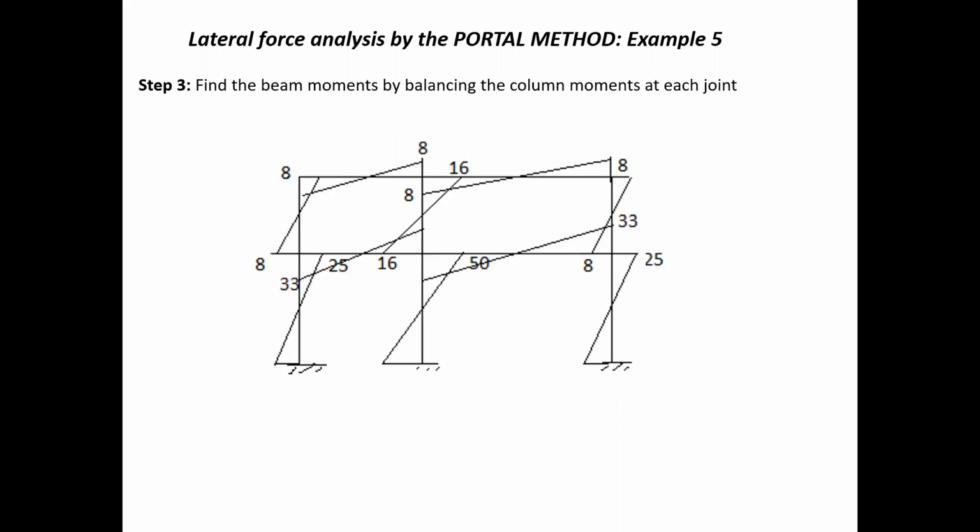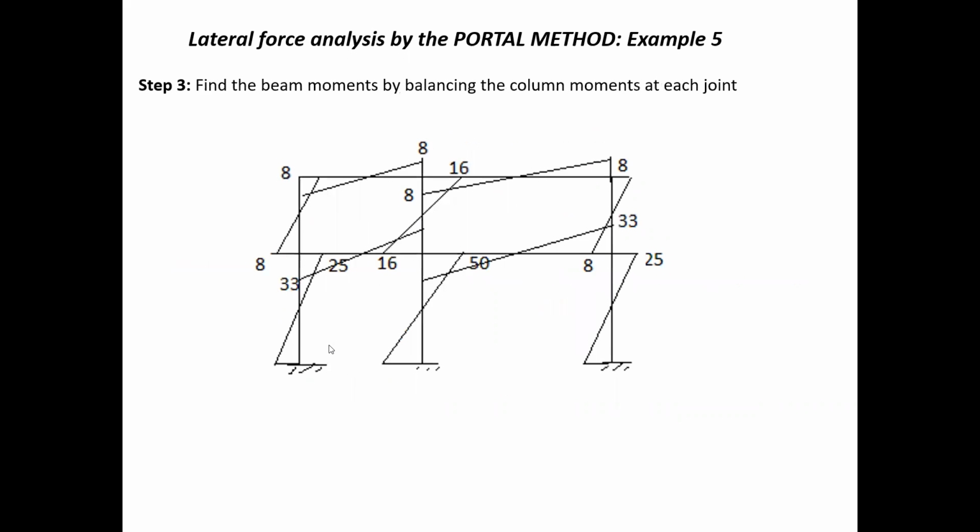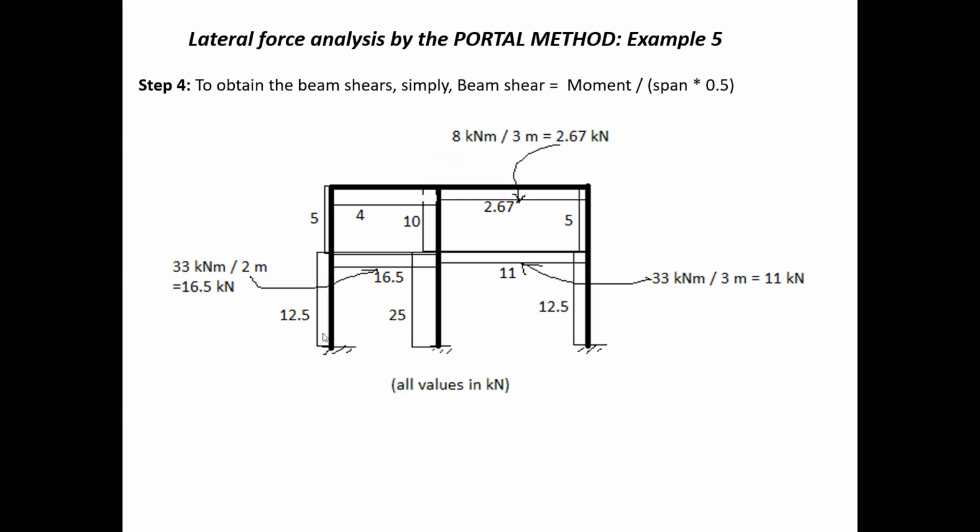Hang on, let's have a look here. You've got 25 plus 25 is 100 divided by 4. Of course, so you got a reaction here. Just hang on, just have a look at it again. You got 25 on the end here. Okay, plus 25 is 50. Oh, sorry, 50 divided by 4, brain stop. Okay, so they've got a total moment of 50. Okay, 25 plus 25 and divided by the length is 12.5.